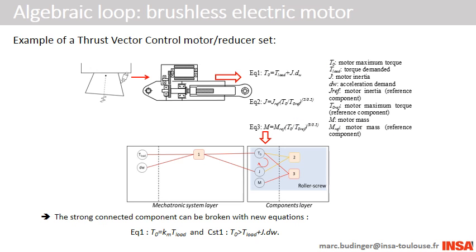The last typical problem is the existence of an algebraic loop. Here, the choice of a motor, based on its max torque, depends on its own inertia, which means we have to know what motor to choose before choosing it. This algebraic loop can be broken by admitting that the inertia torque is negligible to evaluate the max torque, which allows us to choose a motor. The global torque with the inertia can subsequently be evaluated and compared to the torque of the motor we selected.